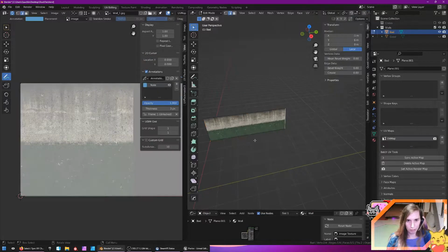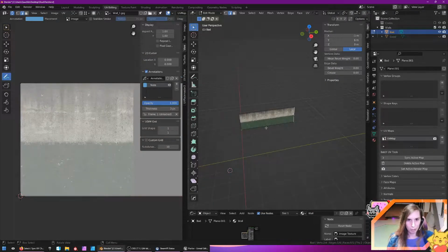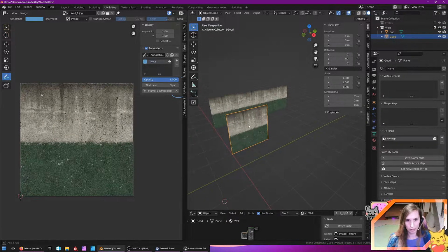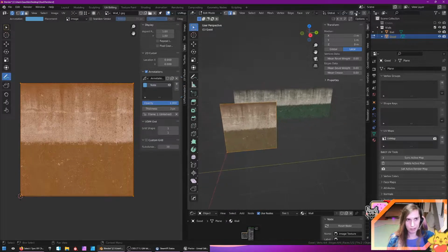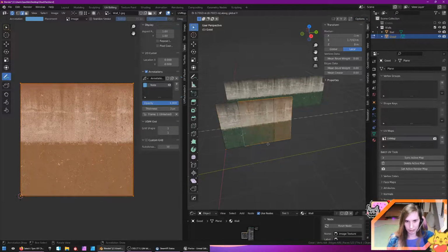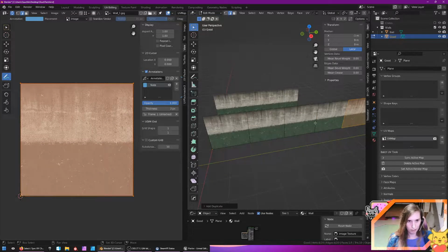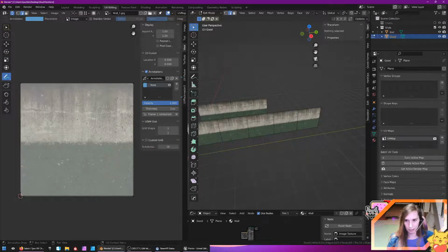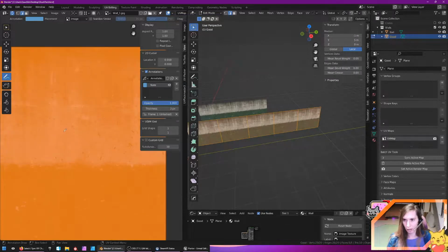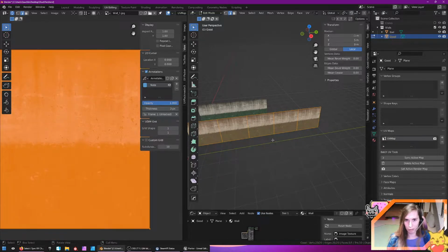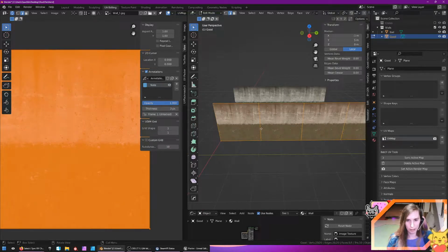Now, to build something like a wall, I recommend building it in tiles. So I have this element here. I turn off correct face attributes, and then I move the whole element. Do this a few times, and as you can see, all elements are stacked on top of each other. This will look great in the Quest, and you won't have any pixelation.